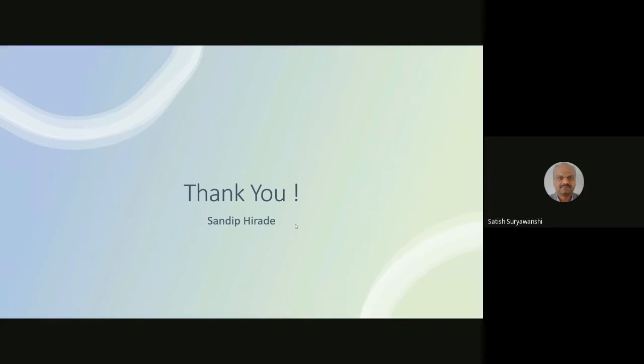Sandeep, sir, you have mentioned the convergence of the solution. From those particular results, how will we come to know that the solution is converged? What is the criteria to decide whether our solution is converged or not? Basically, in order to see whether your solution is converged or not, your residual error should be low. That is the first criteria. How do you select the residual error?